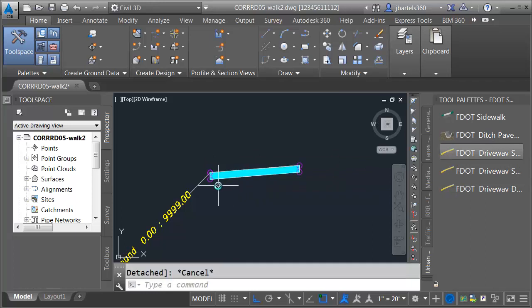Now that may seem unusual. Why are you starting with a slab if you don't want the driveway? Well, there will be some places where I want a little bit of driveway in the flange areas. In the event this slab does not find a target, it will have no width, so it will not display. So we'll look at this condition in a little bit.